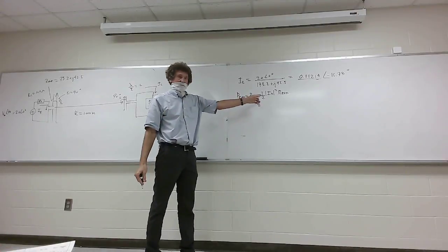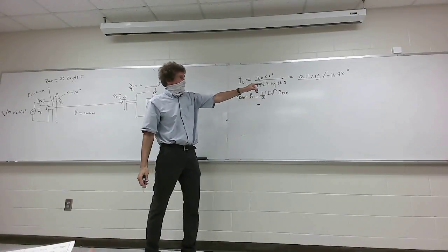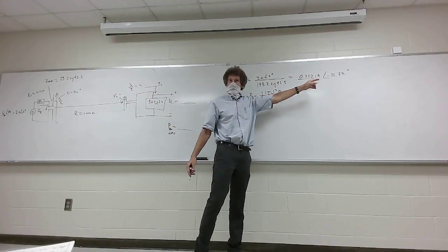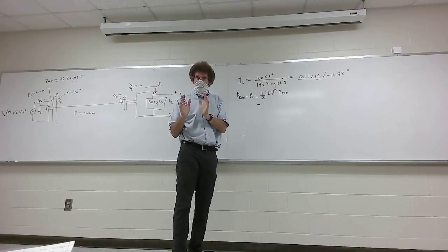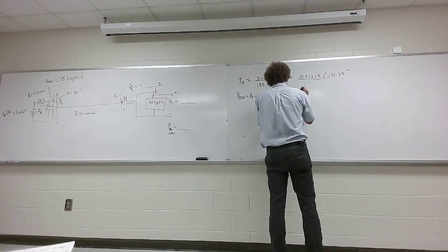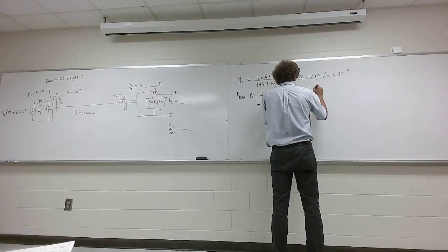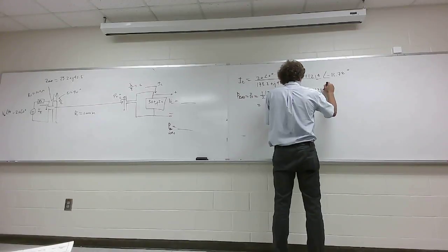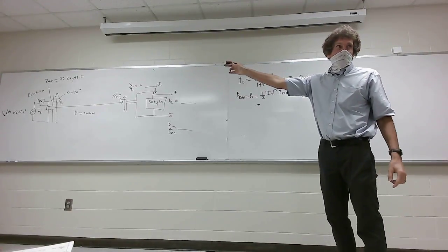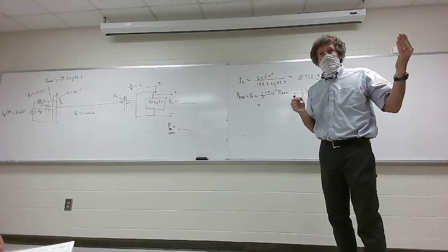Now that's a magnitude, and what I see people do, they'll take this number, if they get a real and imaginary part, and then multiply them together. You gotta take the magnitude, just the magnitude you worry about. So this is 1/2 the magnitude of 0.11214 squared. And what's the radiation resistance, class? 73.2, right? It's the antenna's radiation resistance.